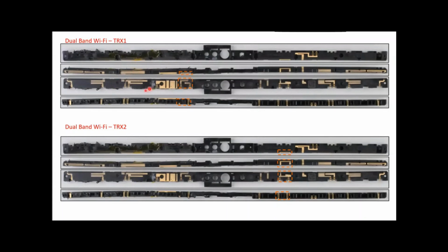So this LTE antenna here and here, and this Wi-Fi antenna here operate at nearly close to 2.4. The filters that we're using in this LTE don't have enough of a steep roll-off to stop all the interference that could happen, or LTE from interfering with Wi-Fi. So we have to try and enhance the isolation between them to improve that. And this structure here was actually developed using an AI algorithm. We developed an AI algorithm to work out what it should look like to improve the isolation. And that's what it came up with, and it actually works pretty well.